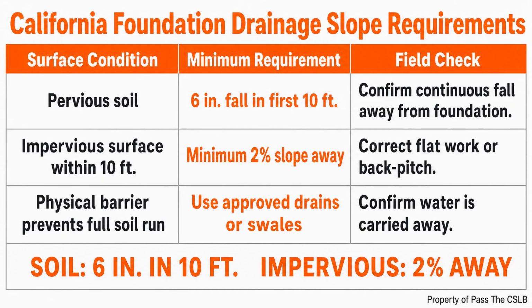Fourth, pre-mark excavation in white. Give the required notice. Preserve the utility marks and hand expose within 24 inches on each side before powered excavation. Fifth, keep layout geometry separate from legal location. The 3-4-5 method can make a corner square, but only verified control can put that square corner in the correct place. Sixth, carry elevation control through finished floor and final drainage.